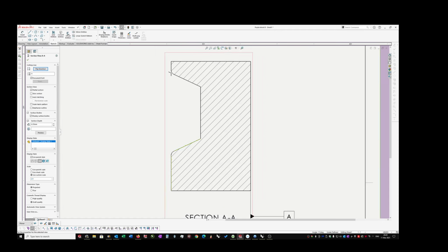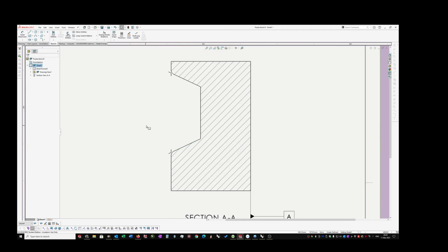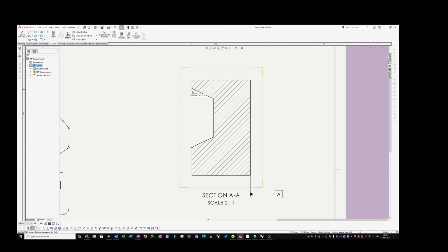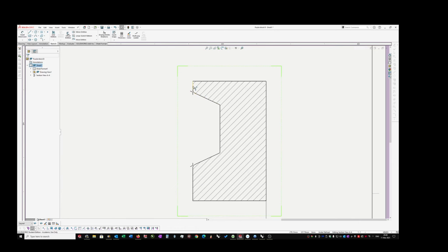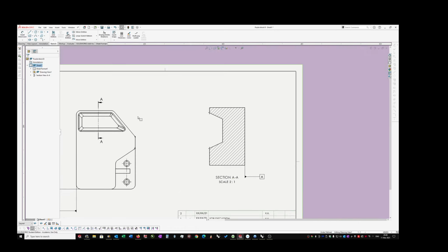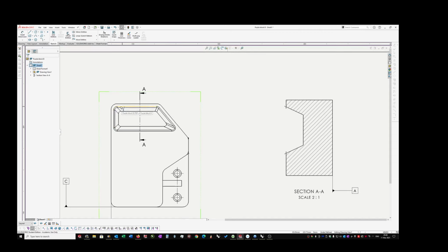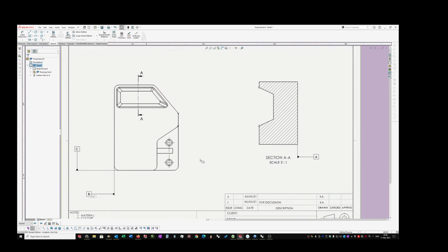So you've got two lines selected. Click on the point and it inserts. Okay, great. So now we've got a reference point which says that line and that line intersect at this point. So these lines here, which don't show you anything other than that there are tangents at those points, now become irrelevant because I've got this little feature here from which I can do everything. Okay, so you've got your datums, you've got your center lines, and you've got your theoretical points of intersection or witness lines.